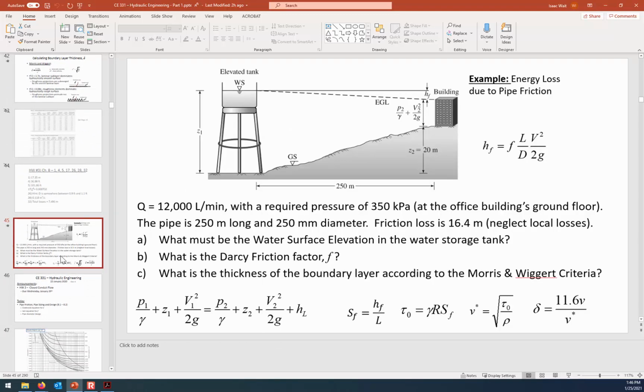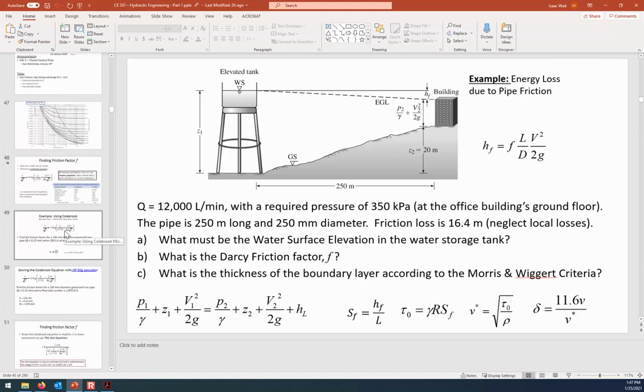The diameter of the pipe is 250 millimeters, and so epsilon is 0.001 times 250 millimeters. This is going somewhere, don't worry. So epsilon is 0.25 millimeters. We're going to be able to now figure out what the pipe is made out of.